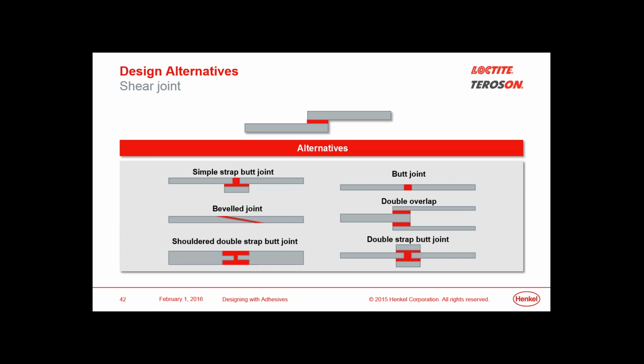This slide is simply meant to show that there are very simple geometric ways to increase the bond integrity. Each of these joints, except for the one on the top right underneath, that's simply a butt joint, two points basically right together. All of the other alternatives are superior to that because in that particular case you have very little flexural strength. All of the others have augmented the bond joint design by increasing the area, by changing it to shear type of motion, and eliminating potential peel and cleavage failure points.